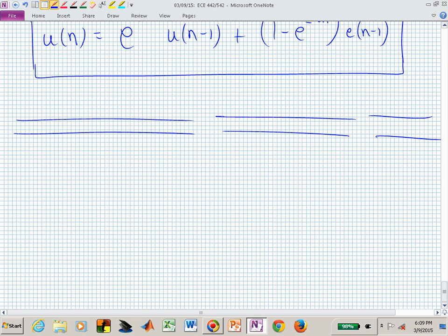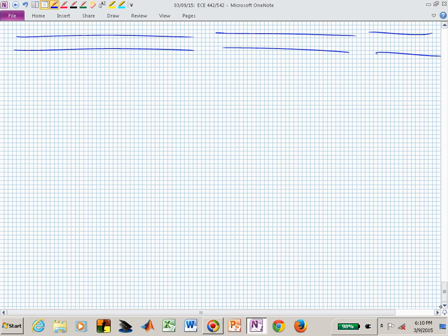No, it means we don't have any finite zeros in the S domain, G of S. If it's a pure 2-pole system, we don't have a zero floating around. That's what we're using or assuming to derive these relationships between time domain values and frequency domain pole locations.